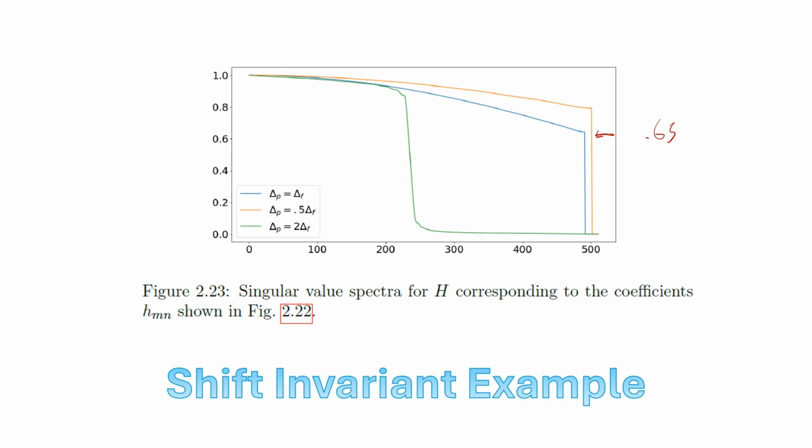In the case of the undersampled system, the singular values go to 0 halfway across the band. Here we've assumed H is a 512 by 512 matrix, but the undersampled system only has approximately 256 non-zero singular values. What this means is that we really only get effectively 256 equivalent measurements, because each measurement will of course be multiplied by its singular values, we'll talk about in just a second.